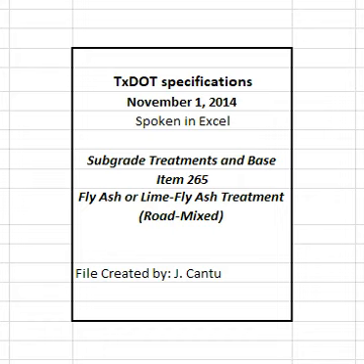4.4.2 Density Control. The Engineer will determine roadway density of completed sections in accordance with Tex-115-E. Perform measurements immediately following completion of layer compaction. The Engineer may accept the section if no more than one of the 5 most recent density tests is below the specified density and the failing test is no more than 3 PCF below the specified density.